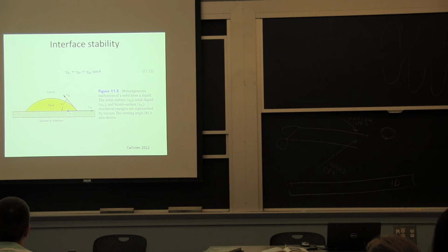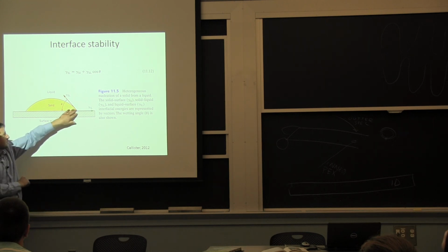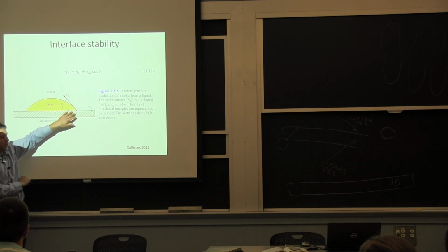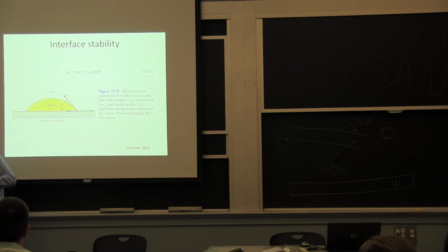So it's all about temperature. So if you can think of even droplets at ambient temperature. If you ever try to solder something, you'll see that at very low temperature, it will essentially form a bubble on top of the parts that you're trying to weld. But if you go to a higher temperature, now all of a sudden you're bringing on more affinity between the elements, and that allows you to spread and make a bond as opposed to just staying as a little droplet.